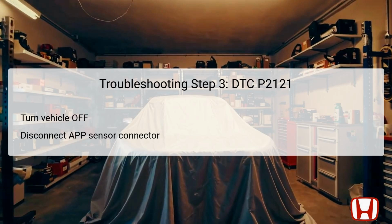For the third step in addressing DTC P2121, the vehicle must be turned off, and the APP sensor 6P connector is then disconnected. This specific action allows the technician to isolate the sensor and perform voltage checks without interference from the electrical system.